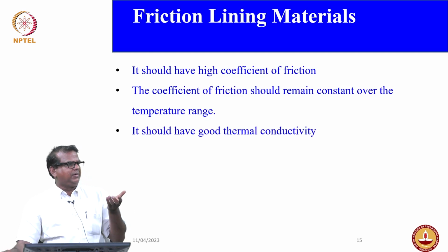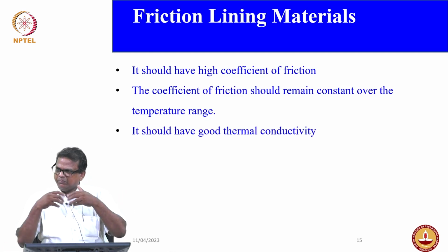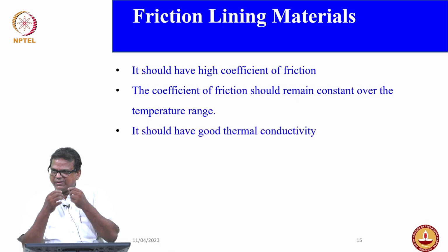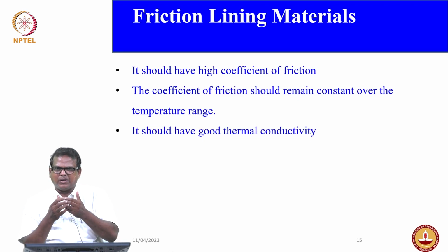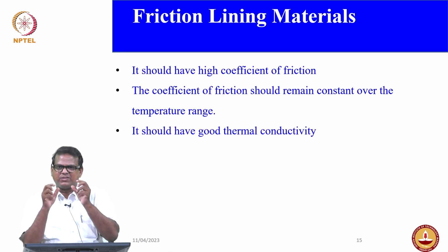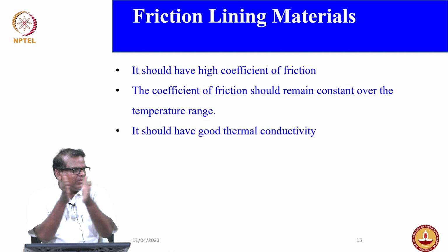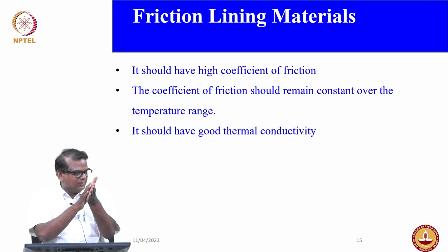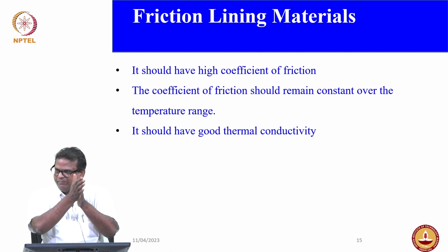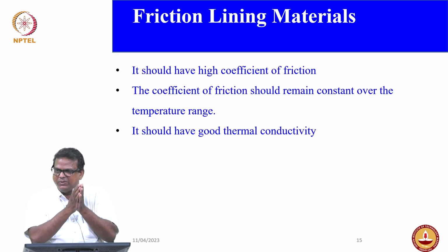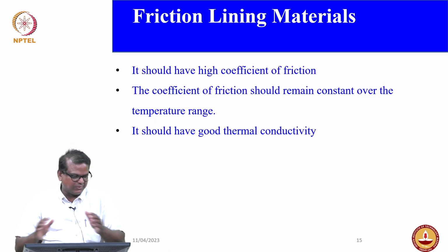Whatever heat is generated in the friction lining must be dissipated, otherwise what do you expect? What is the problem? You will have hot spots, right? The moment you have a hot spot, fading will happen. When fading happens, you cannot hold it. So instead of holding, you will have a slip. You should avoid the slip aspect.